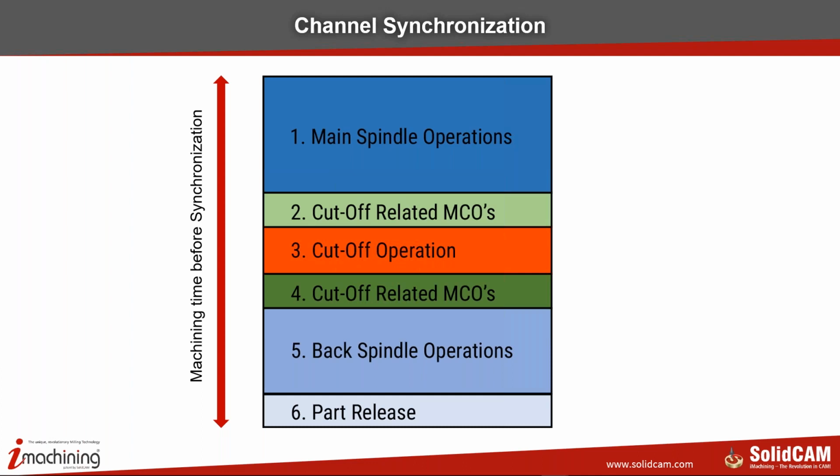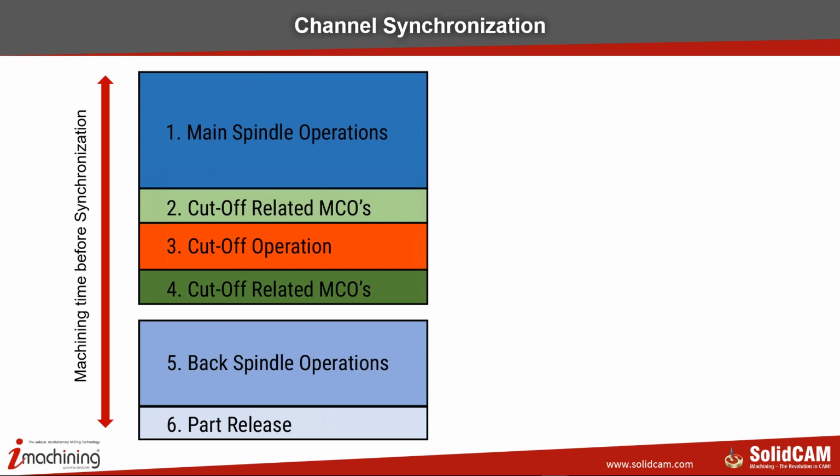To do that, we are using the feature that I showed you. It's called add new workpiece. In general, this means where you would like to cut your program. In the practical situation, the customers on the Swiss type machines usually select the very first operation on the back spindle. So we will use this feature and basically split our G code, or our program, over here. And as you can see, it is removed from the main spindle operations.